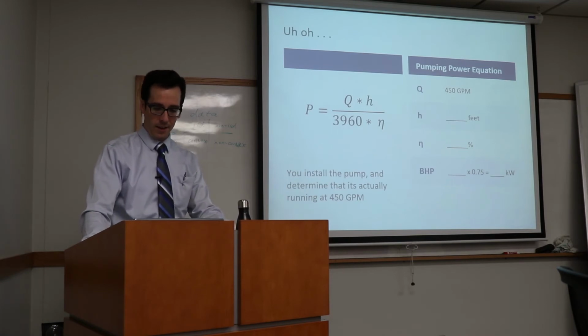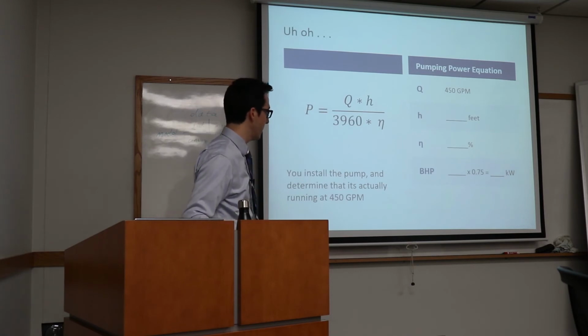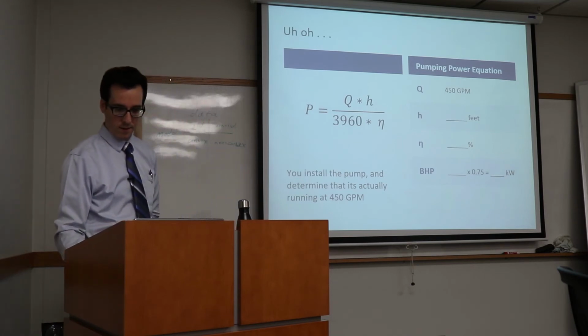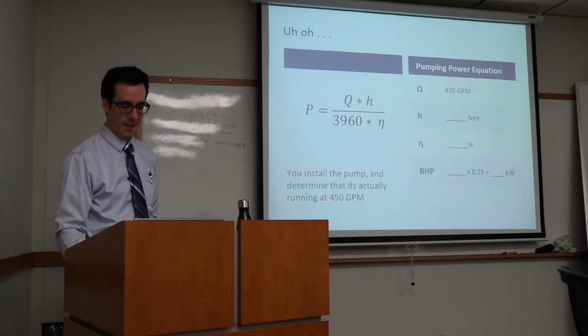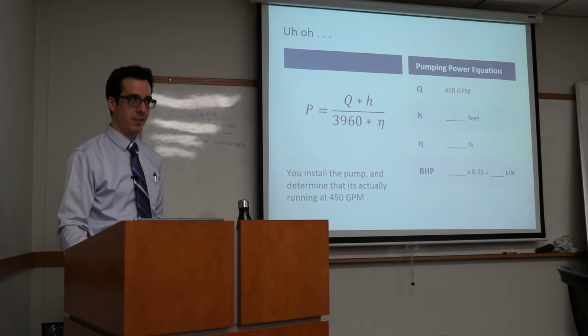Use the curve you have and figure out the new operating conditions at the new flow rate. Same head? No, your head will have to change. Good question. So start with the flow rate. That's given: you take some measurements and say, whoa, it's going at 450 instead of 370 or 350.